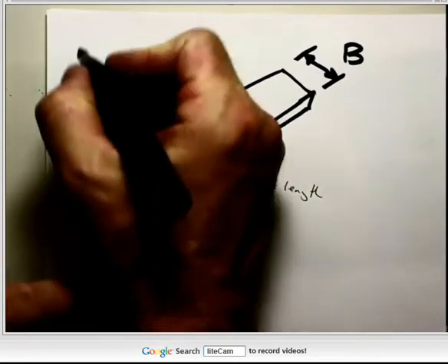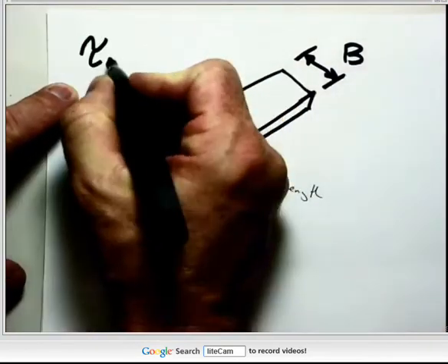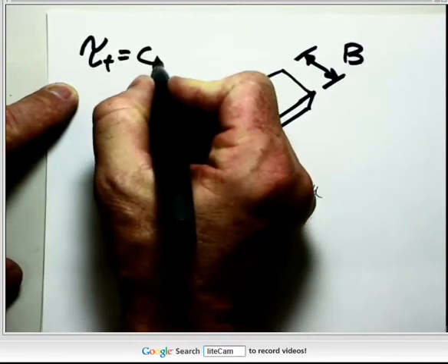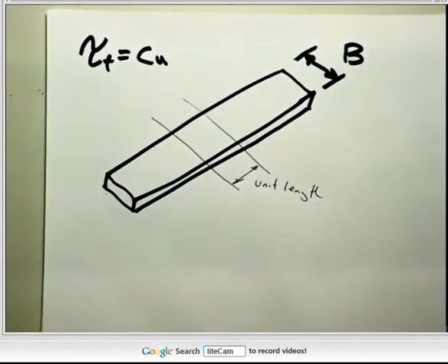Well, to keep life nice and straightforward, we've got a material here where the shear stress at failure equals Cu. So, for this particular case, when we have a failure surface, we're going to get shear stresses develop on the failure surface. And in a general case in soils, we have to say that the shear stress on the failure surface is c' plus sigma' tan phi.